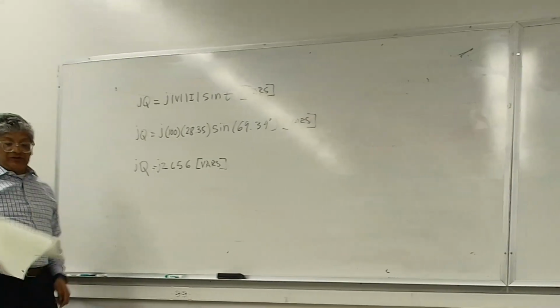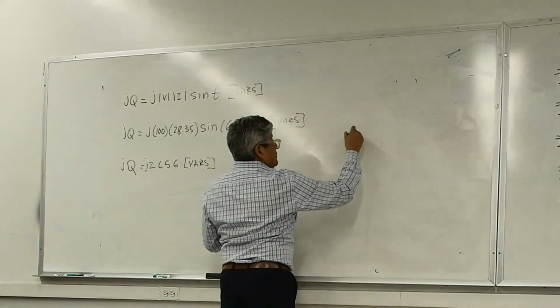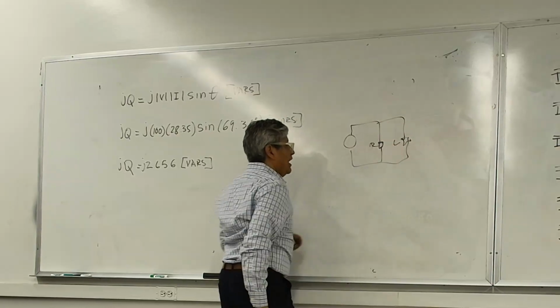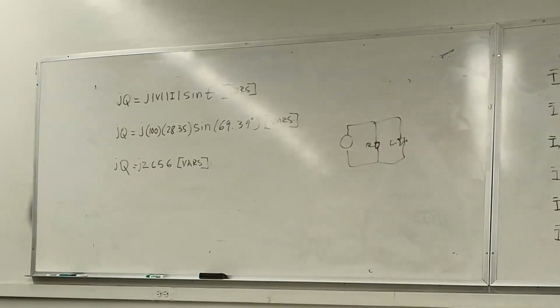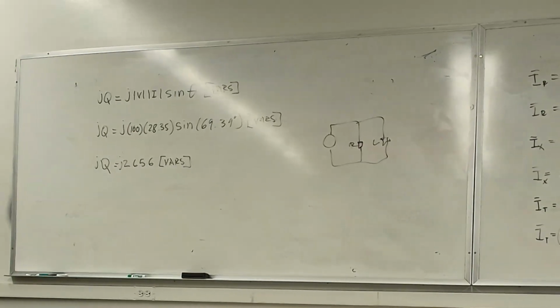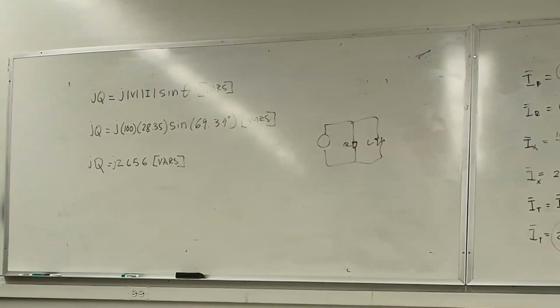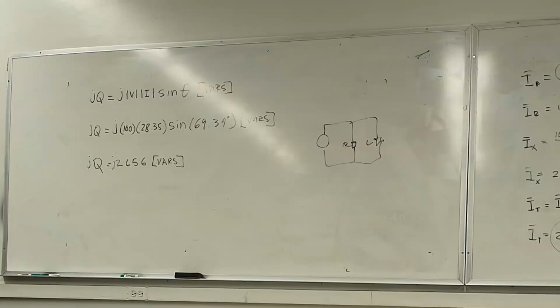Okay, look at the circuit again: a resistive and an inductive load. That's the amount of real power it's consuming, and that's the reactive power it's consuming. Let me ask you to look at the magnitude of the real power and compare it, just a quick comparison, with the imaginary power. What can you tell me? If you're comparing those two magnitudes, 1,000 versus 2,656, you're telling me that this is almost 2.5.